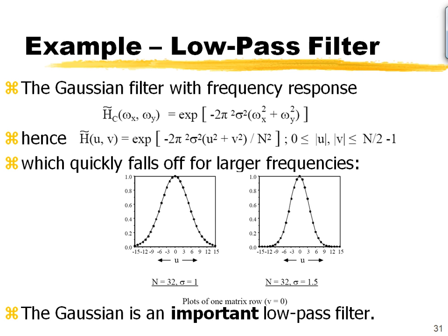I design a Gaussian in space, it's not going to end up as a sinc in my Fourier domain, and vice versa. So it has nice smooth properties, and it's very easy for us to design a Gaussian filter. Remember, the Gaussian is expressed simply by a couple of parameters, right?